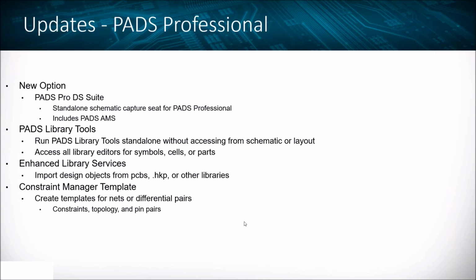And then the last thing for PADS Professional, Constraint Manager templates. We have the ability to create Constraint Manager templates directly from certain nets, how you have them set up, and the constraints associated with those net classes. This can be great for setting up DDR very quickly, and it will allow you to use those Constraint Manager templates in other designs. Okay, so Xpedition has had this capability for a while now, and now we're just bringing this into the PADS Professional space.